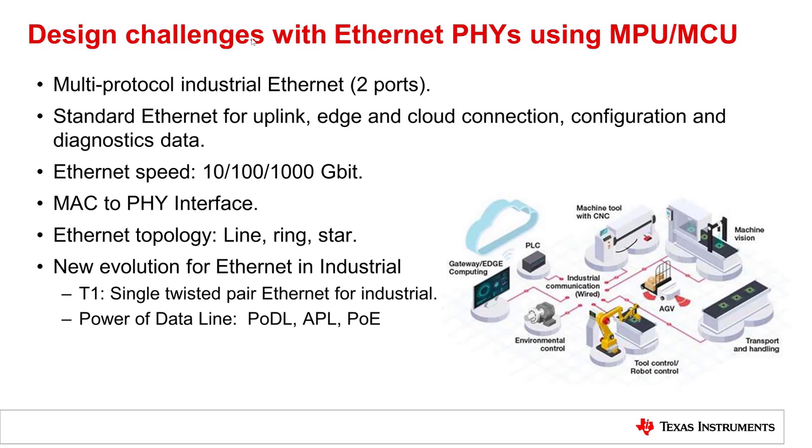There are different design challenges with Ethernet PHYs using processors. One of them is what kind of multi-protocol industrial Ethernet do you want to use? These protocols typically require two Ethernet ports. Then in your application you may have a standard Ethernet for an uplink, for an edge or cloud connection, or for configuration and diagnostic data.